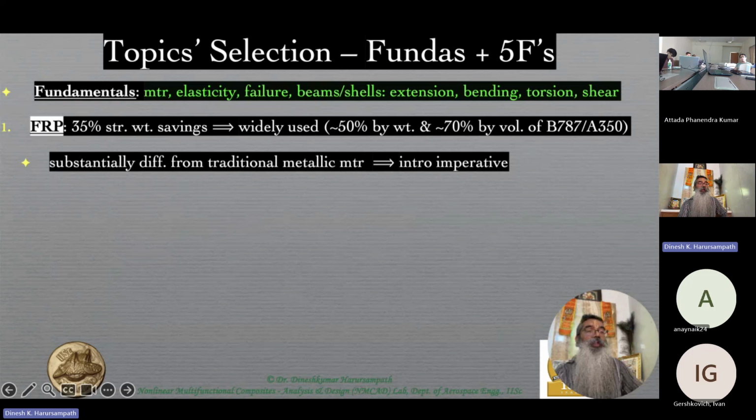as most of you might know. The plastics that we are talking about are the most common example so far has been epoxy, but as I said, we are moving more towards thermoplastics, with some level of reusability, if not for flight vehicles, at least for some other industry, and therefore we are not causing a huge environmental damage by using some of these thermosets, which have been used predominantly in the last 2 or 3 decades of composite usage in flying vehicles.